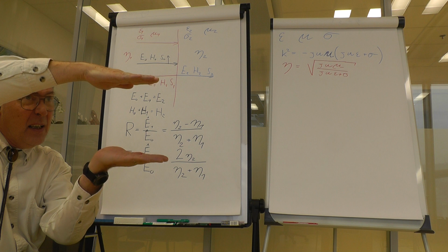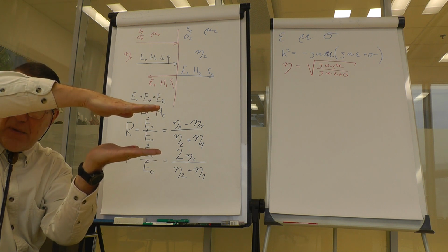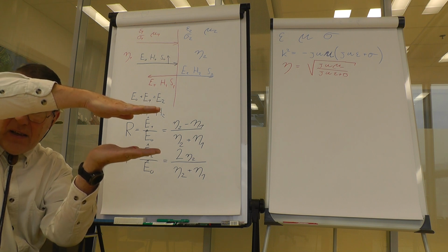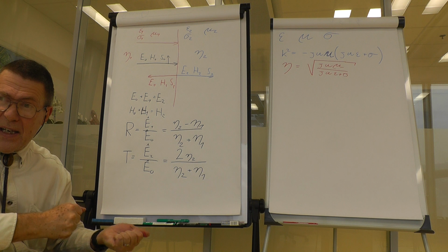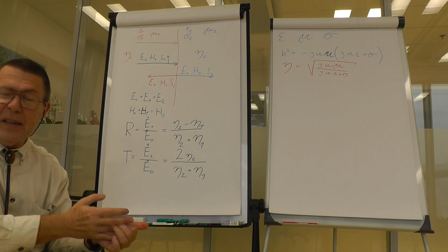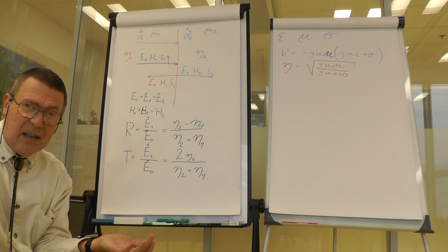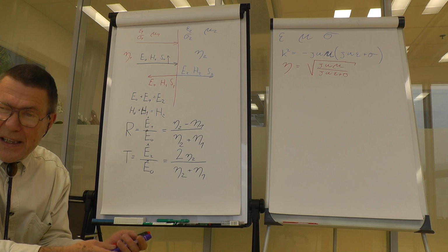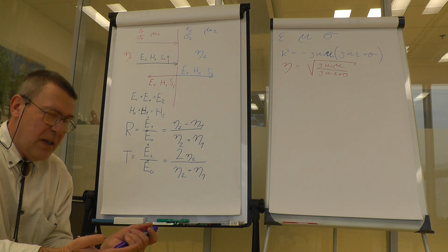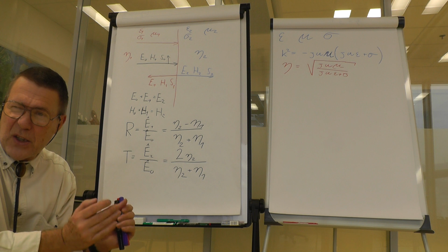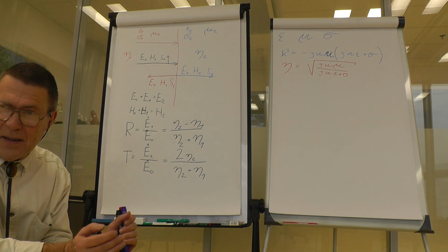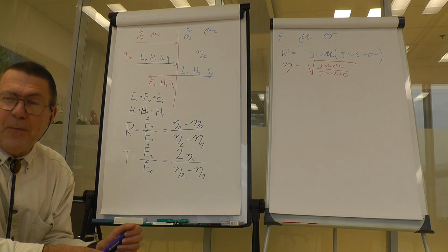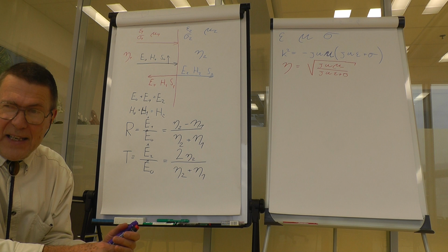We can then stick the measured material in between those two plates and measure the current that is caused by imposed voltage, and we can measure also the current or the displacement current, the capacity of that capacitor, and that would give us permittivity, and we are able to arrange similar magnetic measurements, and we can measure those values at DC.